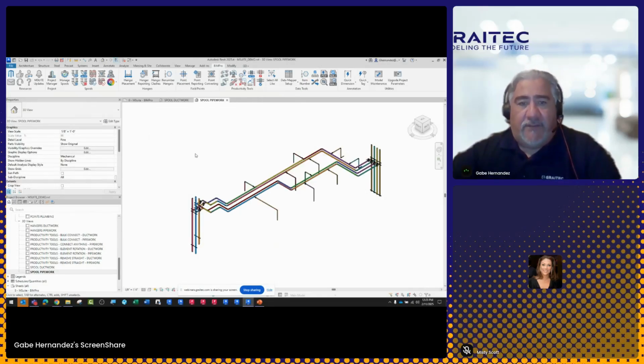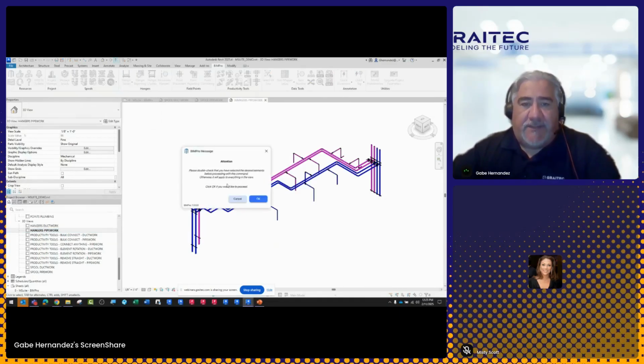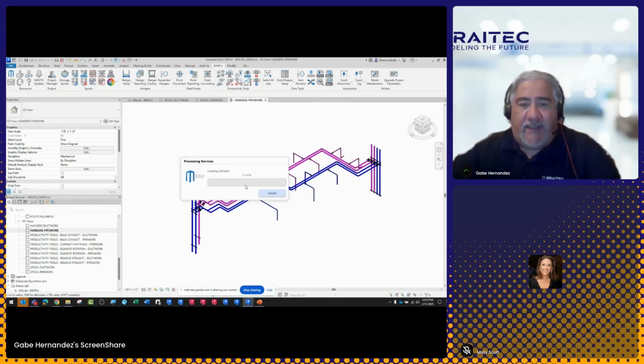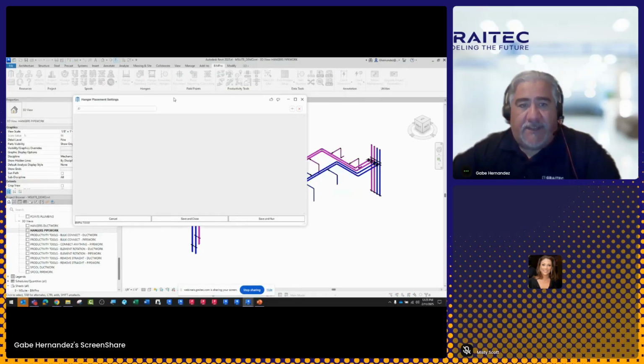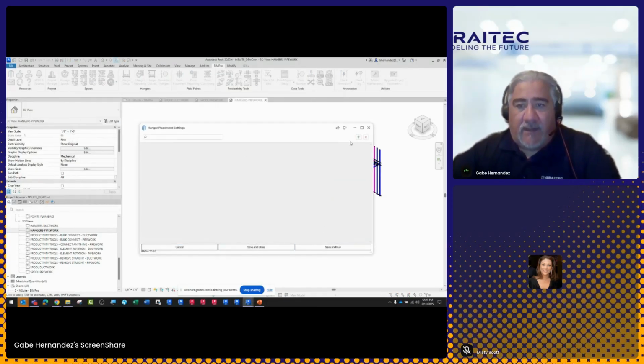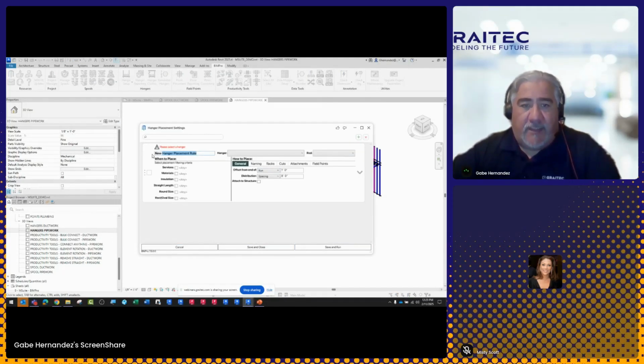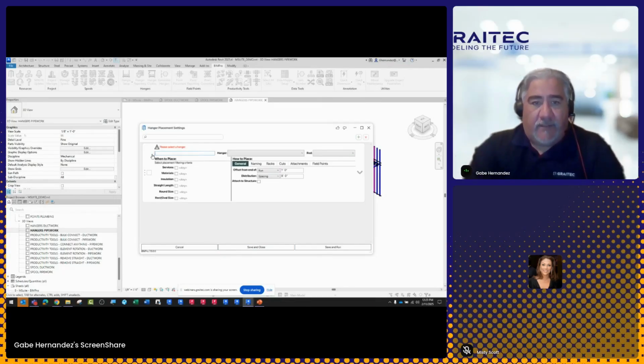And then, again, I know we're short on time here, so I'll go and do some hanger placement, right? So I'll show you the tools for hangers. The command, again, you can do a hanger setup here. And what you would do is set it up to provide the type of hanger that you'd like. Right, so you would set up your rules in here. You can add a rule, give it a rule name, hanger 1. You can do it by surface or service here, right?